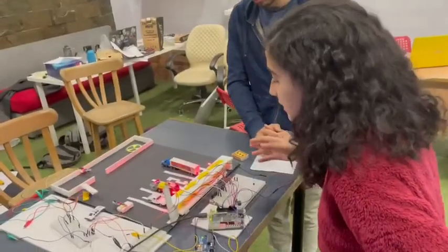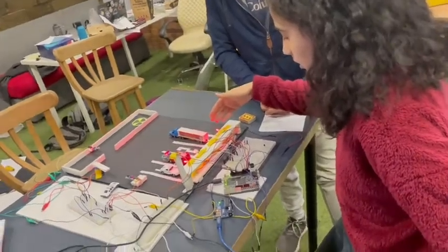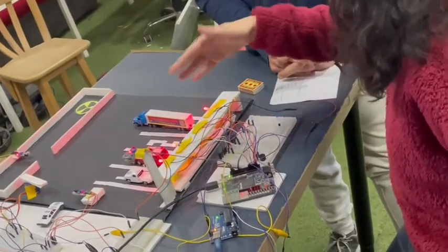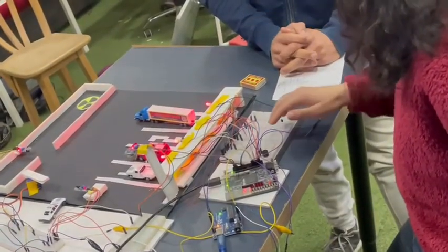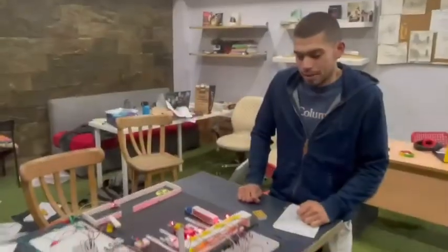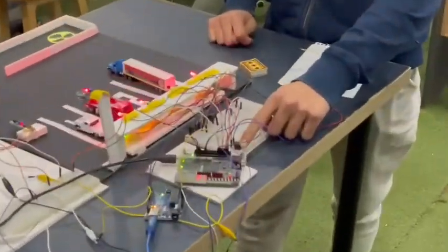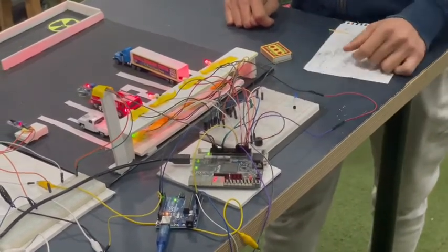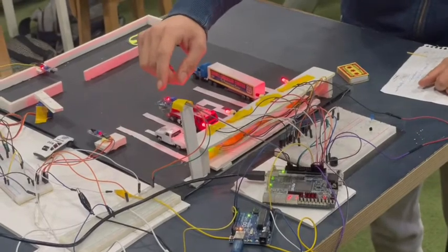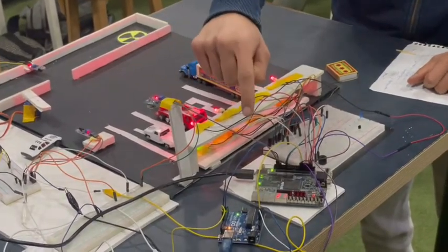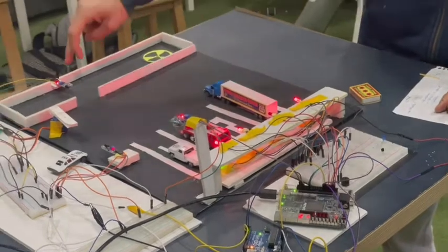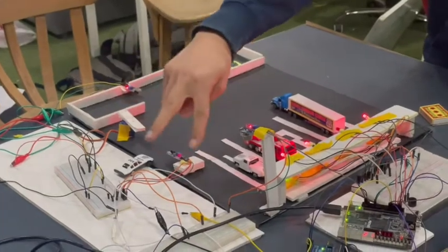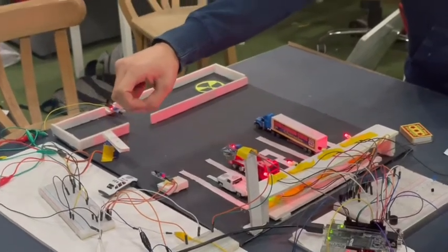Here we have the 4 IR sensors and the 4 LEDs. The outputs are connected to the FPGA, and the VCC and the ground are connected to the breadboard. So next we have our buzzer, which is connected to the FPGA and also connected to the common ground. There we have our smoke sensor, which is connected to the Arduino that we use as a power supply in this part. And here we have our 2 IR sensors and our servo motor, which are connected through these parts using these 2 breadboards, also to common ground and a VCC.